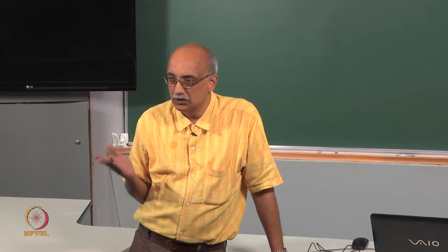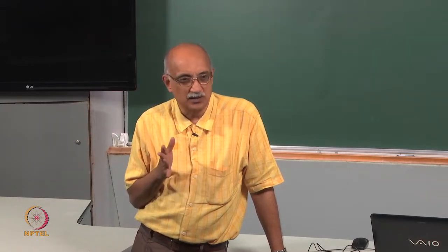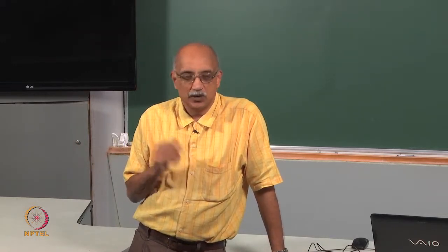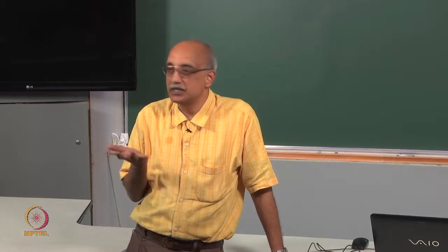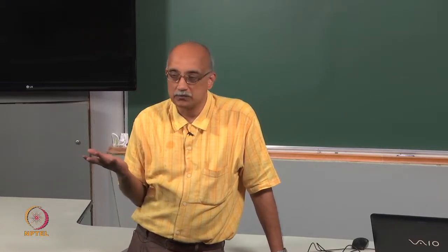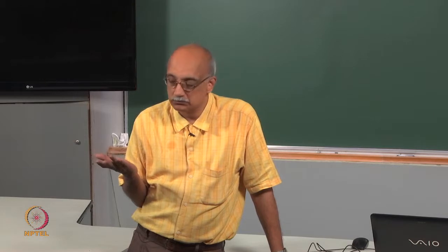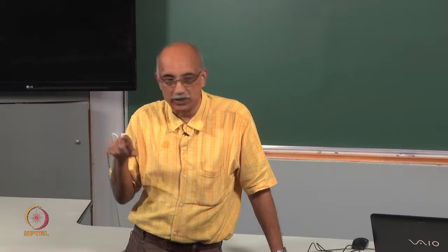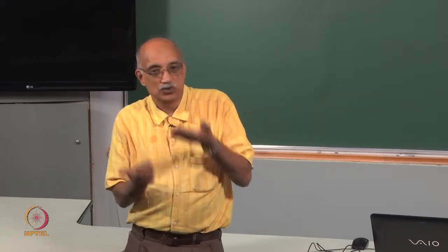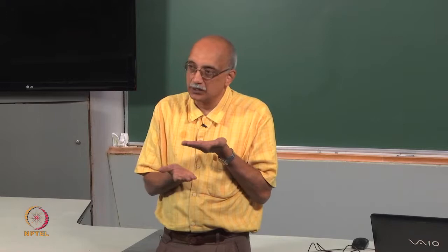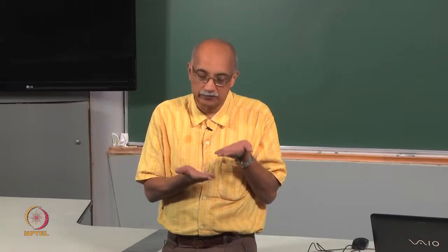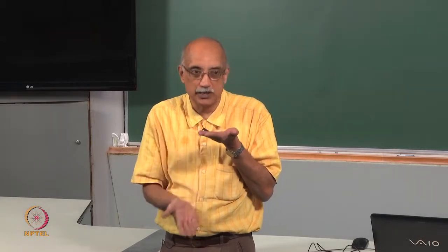from school, sieving, screening. I am sure you study those things, and I have seen those in your 11th standard, 12th standard textbooks. How does it work when you use a sieve to separate particles by size? What does a sieve look like? It's got a lot of meshes, right? Square shaped meshes, and you stack the meshes in such a way that the coarsest mesh is at the top, and then the meshes get finer and finer as you go down the stack.